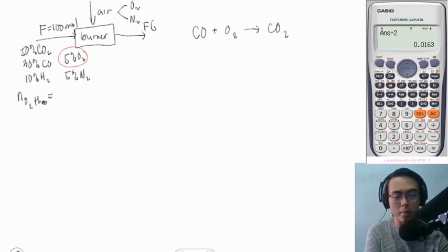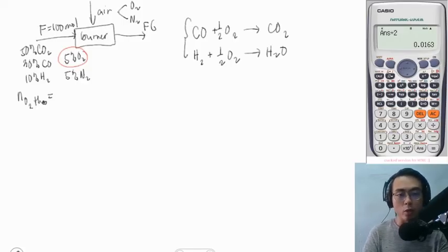To balance, that's times 1/2. Next is hydrogen. So hydrogen is still combustible. Next, oxygen. So oxygen is not combustible, but we have to subtract this later. And then finally, the nitrogen is not combustible. So all in all, we are just looking at 2 terms in our O2 Theo plus another term for the subtraction of oxygen. So this is how it goes.